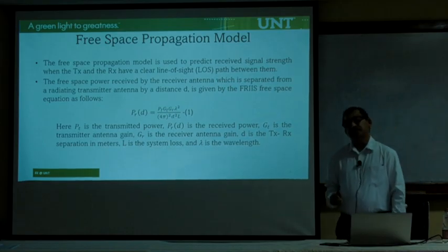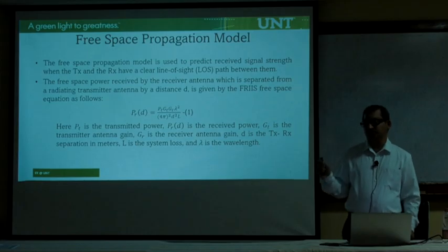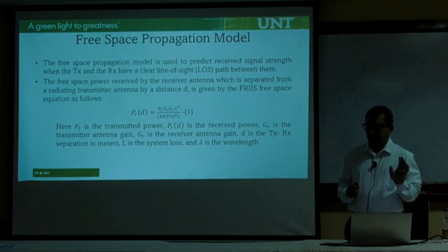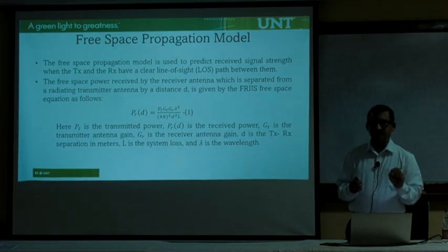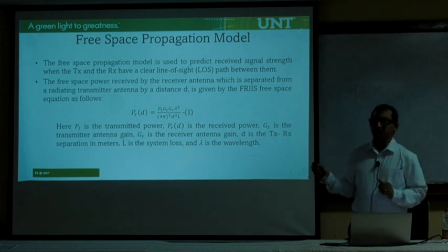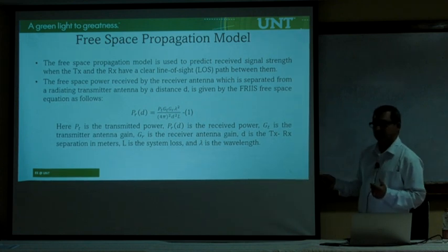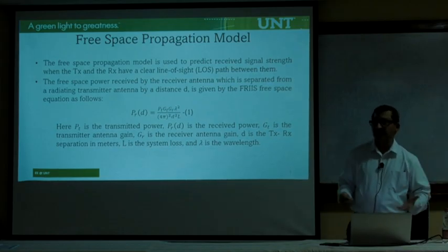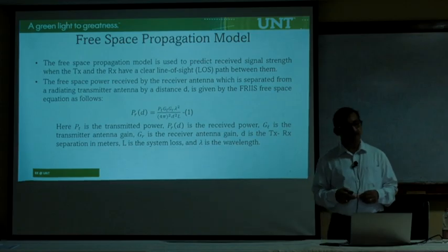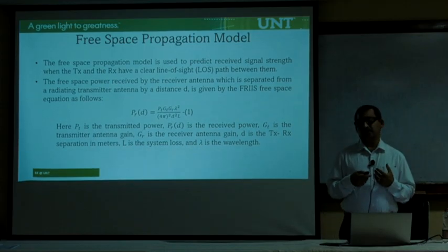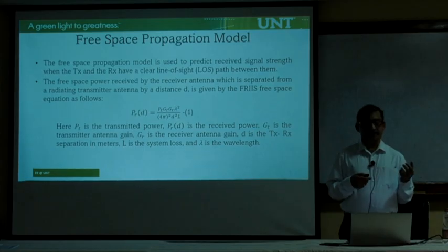So that means you can say it's a function of d power minus 2, right? Keeping other things aside, we're only looking at it in terms of distance. What is what you call the path loss exponent? You can say in free space it is 2 or minus 2. But in an urban environment, like there are so many buildings, or sometimes even in a rural environment, there are a lot of, for example, trees or shrubs.